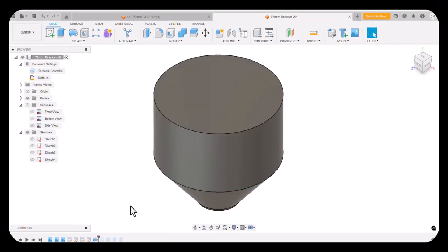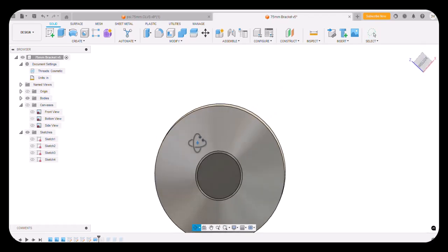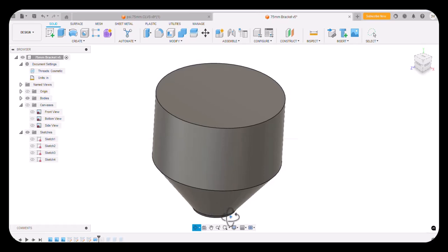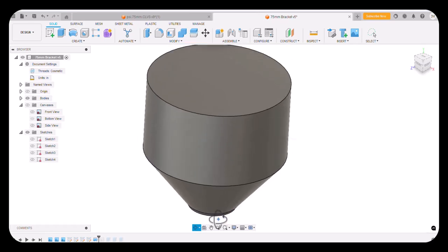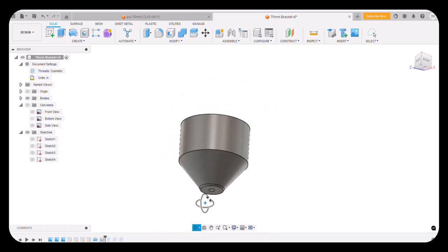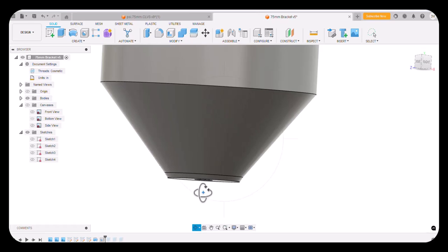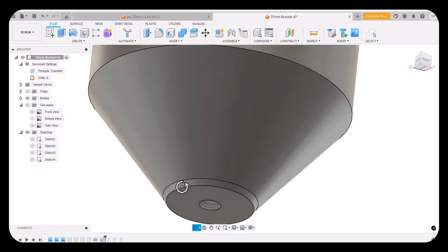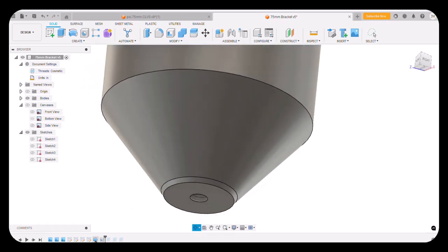So I decided to give consideration to an operation sheet. That is the order in which we will machine the parts. So we have our first operation, which would be the revolve cut on the angle of a cylinder. And then the next operation I decided is to put this hole through the part, and perhaps we could use that hole then for clamping for milling operations. I might also put the fillet on here as part of the first turning operation.